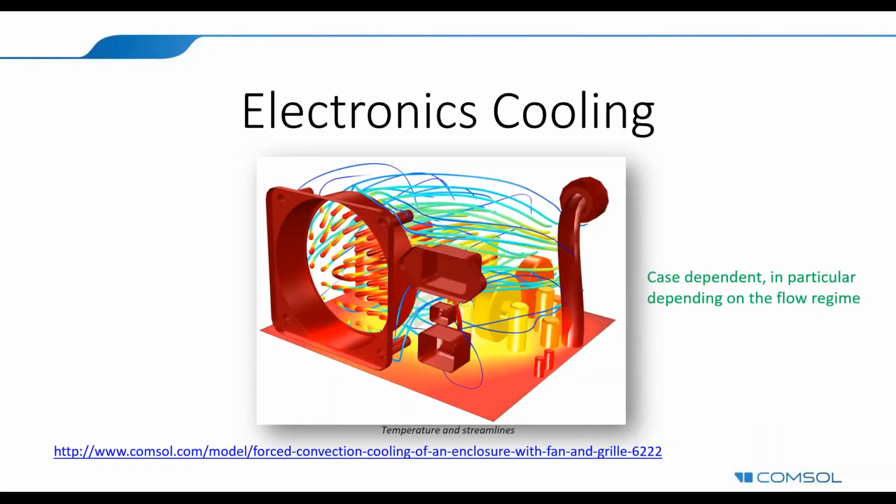For example, in passive, noiseless cooling, where you don't have any fan and just rely on natural convection, the cooling is pretty small, and radiation is likely to be important, maybe not dominant, but at least important. In cases where you have fans and active cooling, the flow motion is probably big enough to dominate, and then radiation is very small compared to convection.